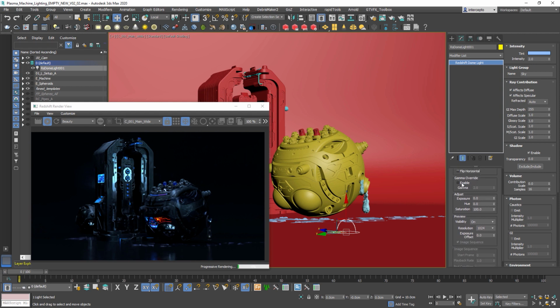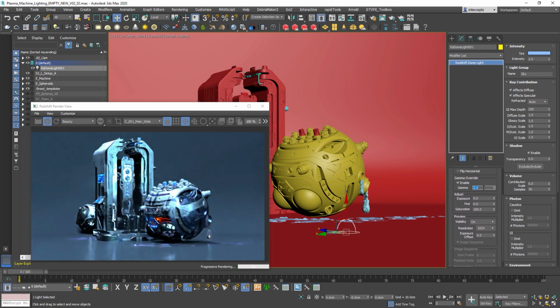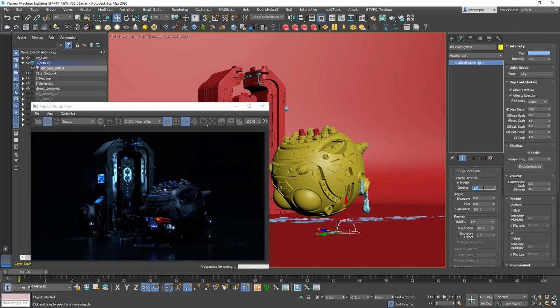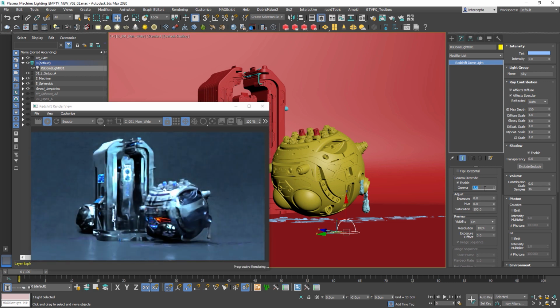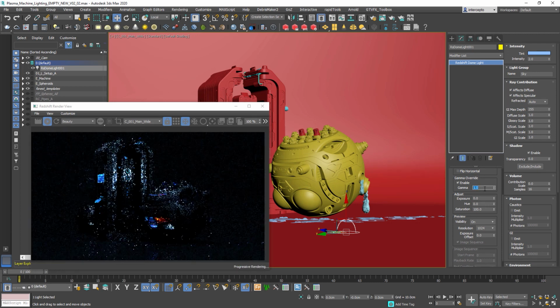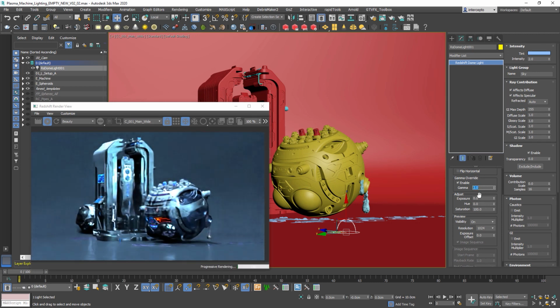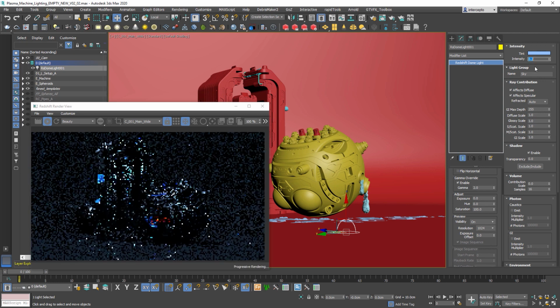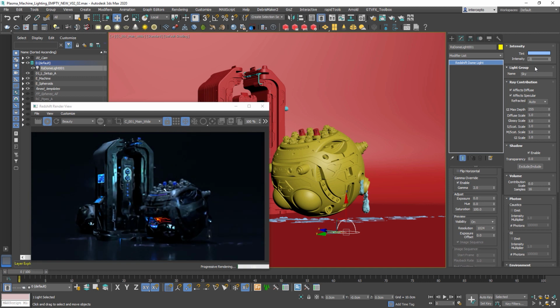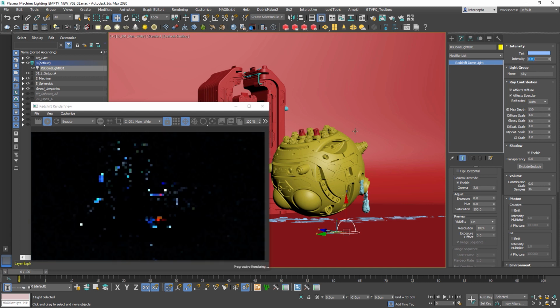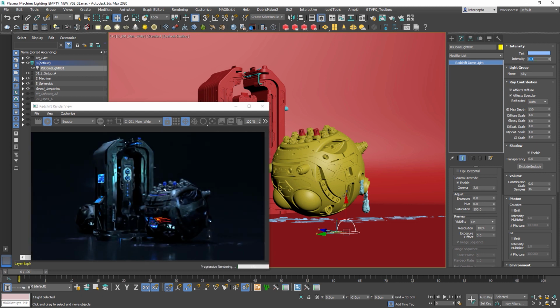One thing that I can also tweak is gamma. By default it's set to 1. So if we leave it set to 1, then it should be as realistic, relatively low contrast, and if I start increasing that gamma, then it creates a more contrasty map, but at the same time it produces more intensity for the light. So what I'll do is I'll set it to maybe 2, but at the same time I'll just reduce intensity to maybe 0.01. I'll actually leave it as 0.1 maybe.